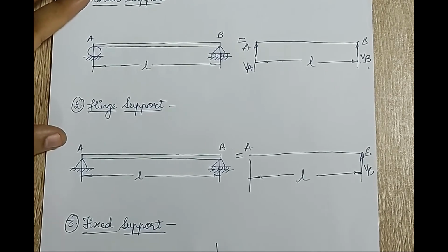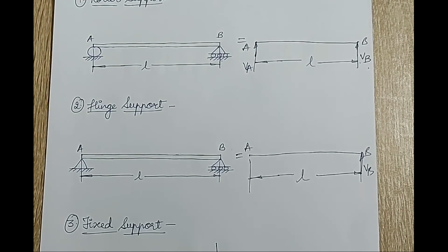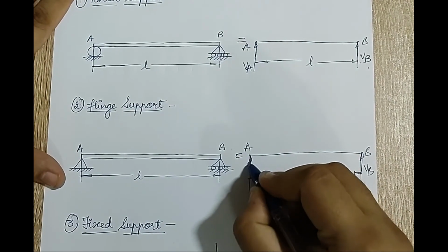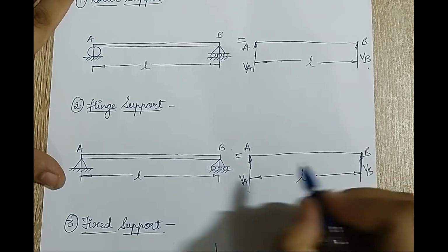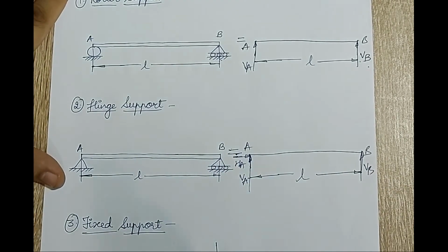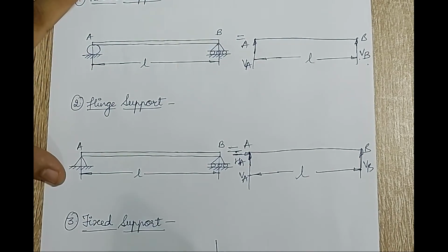Similarly, if you hold the door and you want to uplift it in the y direction, it is not possible. That is not the kind of movement that we expect from a door. So, for a hinge reaction, the object is constrained to move along both the x and the y axis. But it can swing. Hence, there is no moment reaction here, but there will be one reaction in the vertical axis and one along the horizontal axis. So this is my equivalent FBD.